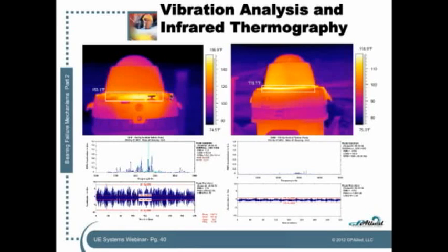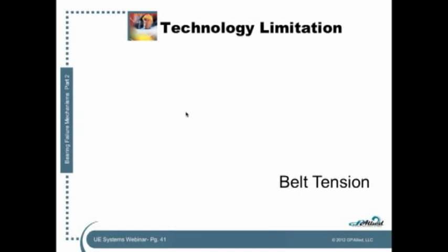So personally, I don't know of a better example that puts vibration data and thermography data in the same place at the same time, showing a nice example of failure propagation. So really, really powerful story associated with this particular slide.